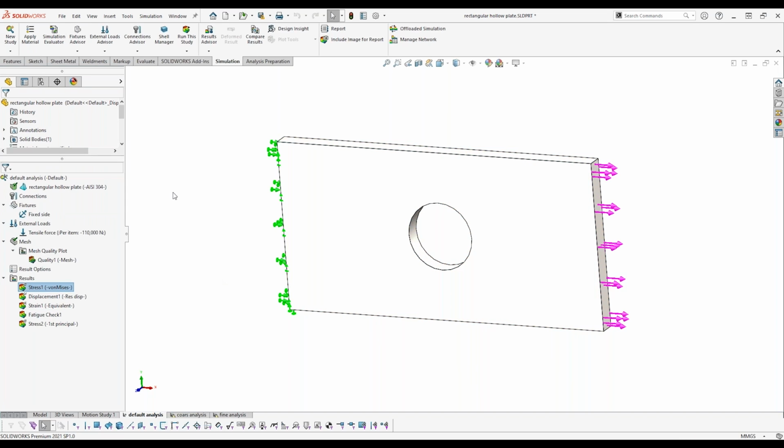In my analysis, the steps are pretty simple. I am already inside of SOLIDWORKS Simulation. I went from my model tab into simulation. It's a simple add-in. It adds a bar up here and you can begin a new study. I usually work top to bottom when I get my information. What do you need to run a simulation? You need a material.